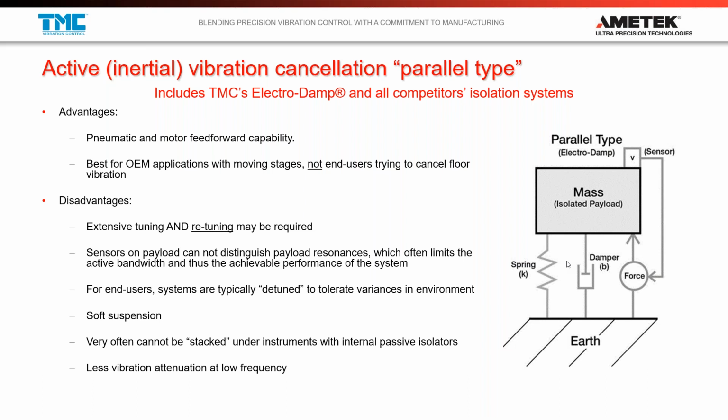And what you do when you feed forward something is you have a known condition on the payload. Maybe it's a motor turning at a known frequency, or it's a stage moving back and forth with a known mass and acceleration. Well, you can get a parallel system to counteract the vibration induced on the payload using that known input, so that it can actually start to react to a known input before that input actually starts happening. So there's a real strong advantage when there's known motion on the payload to using a parallel type system to cancel that out and keep the payload still.